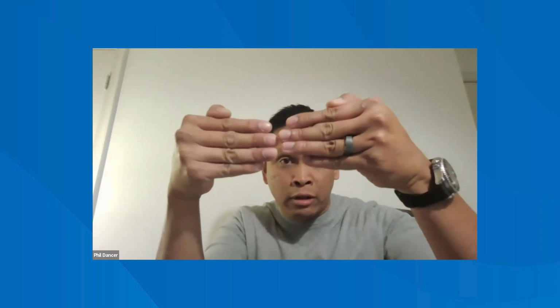Now, let's say Simpson Strong-Tie, for example, the manufacturer Simpson Strong-Tie. They have different types of hangers. They have two different families that you'll typically see out and about. One is the HUS series of truss hangers. What they say is that you cannot have a gap between the carrying member, so that would be like a girder beam or a girder truss, and the carried member exceeding an eighth of an inch between the two components.